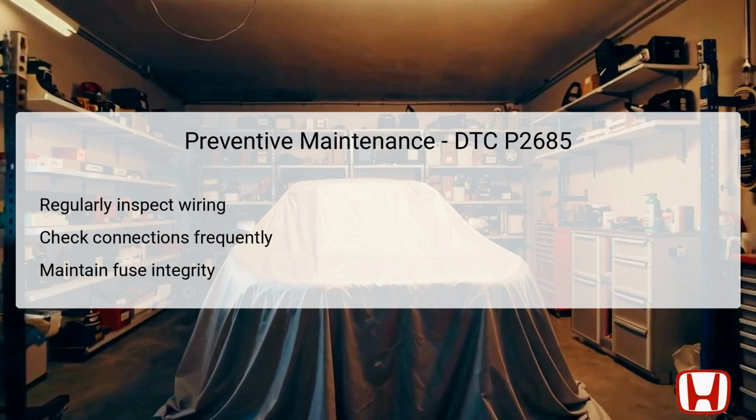reliability. Preventive maintenance plays a critical role in minimizing the chances of encountering DTC P2685 in the future. Regular inspections of the wiring harnesses and connectors associated with the TCM are crucial in identifying potential wear and tear that might compromise electrical integrity.